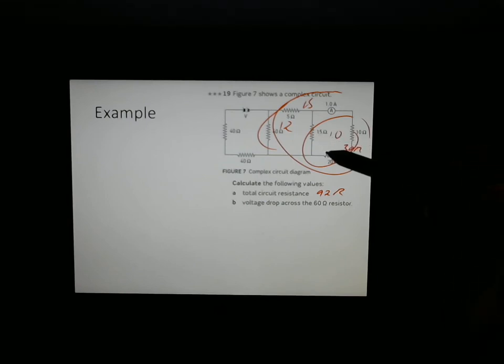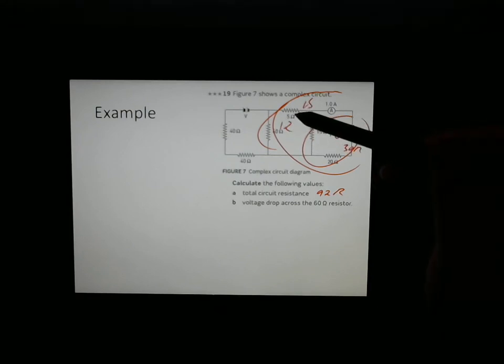And then, since we know the voltage being used, we know the current. And since we have the current, and we know the current here, we could work out the current going through here, which would let us work out the voltage being used up by it. And if we've got the voltage being used here, and the voltage being used here, or here, because remember, these two bits are parallel to that bit, then, because we've got the voltage for this whole bit, we know the voltage for that is there. In fact, I think the next step for this question was in the previous textbook: what is the voltage actually being created by the battery?